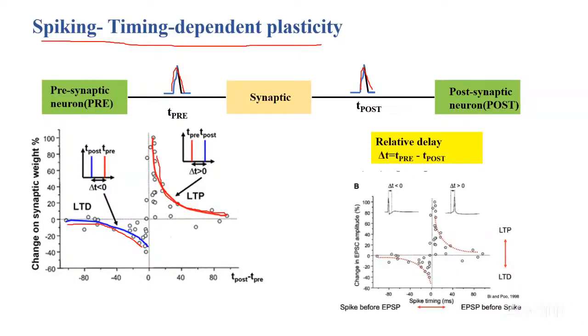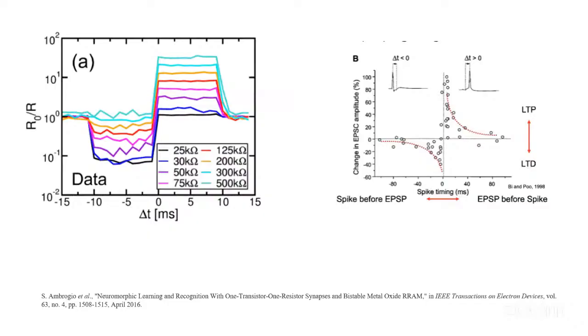Okay, so these results are from an RRAM, where you can see long-term potentiation and long-term depression, two properties which are mimicked by RRAM. RRAM is one of the technologies that is CMOS compatible. And if you see the chips developed by IBM and Intel, which are neuromorphic chips, these are developed using RRAM technology.